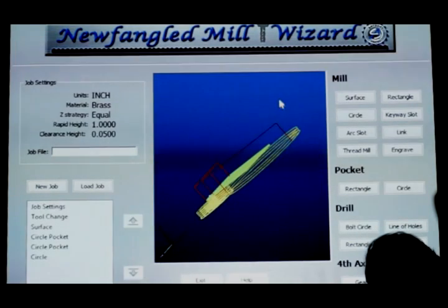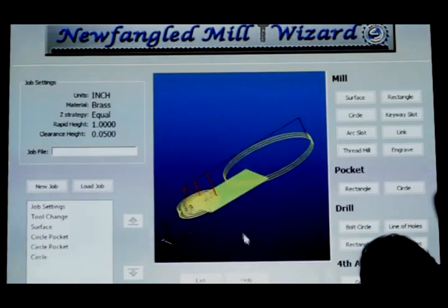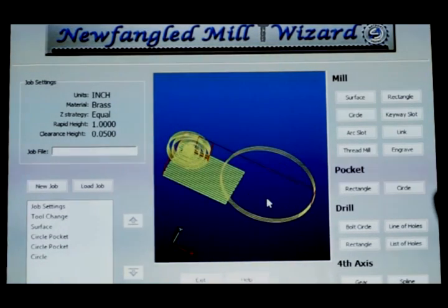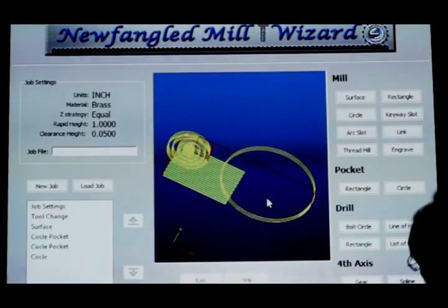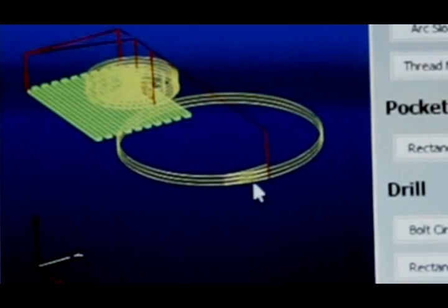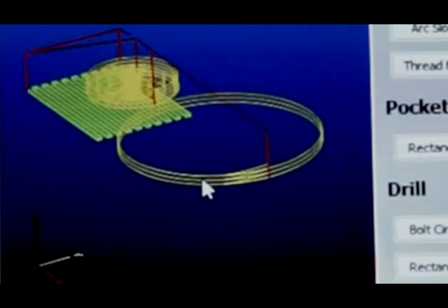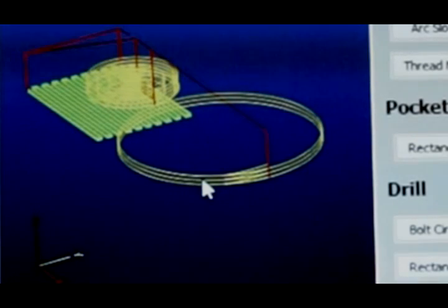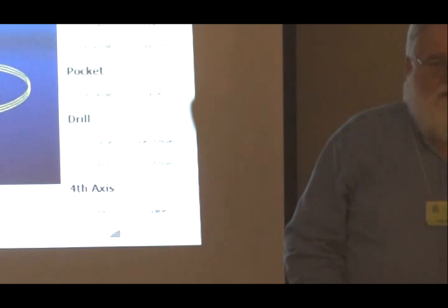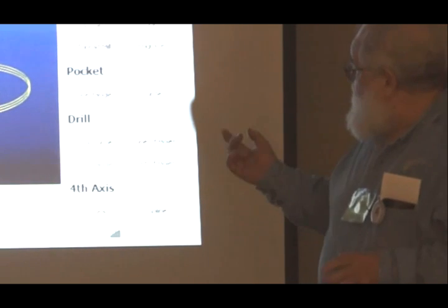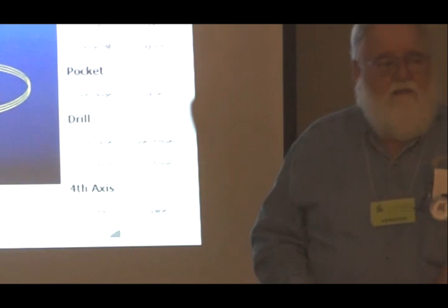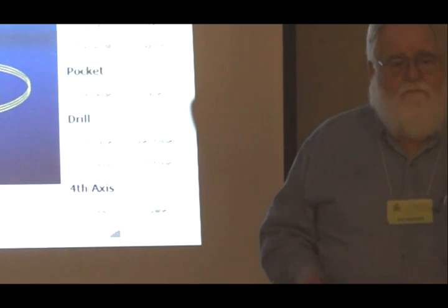So there it is, and you'll see that on this one, I'm only cutting around the circle. Also you'll notice, zoom it up a little bit. See this funny little squiggly in here? That's where I'm doing my ramp down, this sort of zigzag down. We talked about doing a helix down, but in this case, maybe you want the inside, or maybe you want the outside, and it gets kind of complicated in the programming of which way.